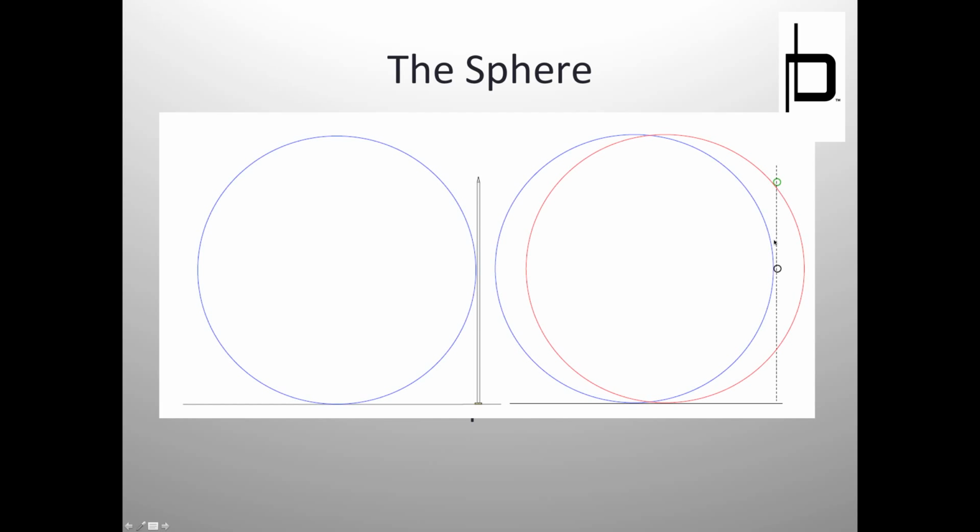Now, people tell me I'm a little paranoid when I talk about this, but if you remember the video, we saw some of the step leaders moving sideways. So we can't guarantee that everything's coming top down and is going to find this wire. It may be coming from the side, and that's why we do the rolling sphere from the side as well. So this is a common mistake a lot of people make. They have trouble with their protection zones, they say, well, it fails. Oh, just raise the wires. While that is a great solution most of the time, you've got to check. You've got to make sure that you're not raising the wires to a point that you're causing the spheres to sneak in underneath it.